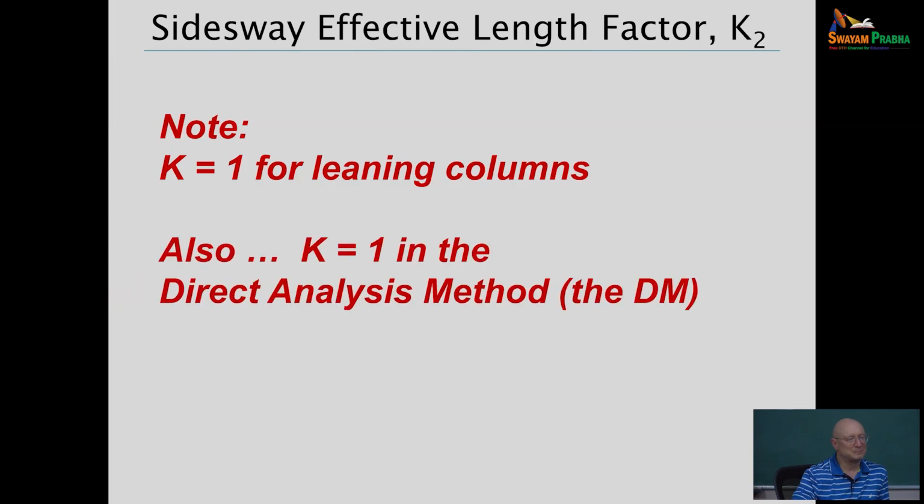So why would we want to? Let's say you've got a structure and you don't want a bracing diagonal going through your doorway, or you need access. Yeah, a moment frame would be a sway frame. That's correct. It's obvious it's always going to be more efficient if you can have walls or bracing systems in the frame. But in some situations, we want to use a moment frame. That's correct.